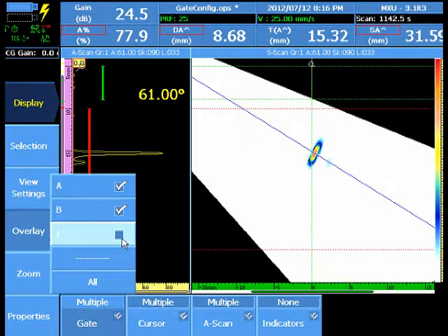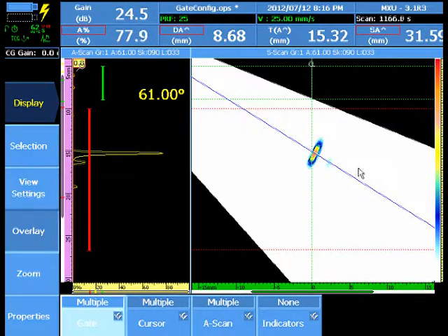Gate I is a yellow gate associated with corrosion mapping and immersion tank applications that allow a synchronization on echo of the A scan, and gates A and B to float on the interface signal. Whether the gates are displayed or not on the various data views, they are active in collecting data all of the time and should be kept within the digitized range of the A scan and S scan.